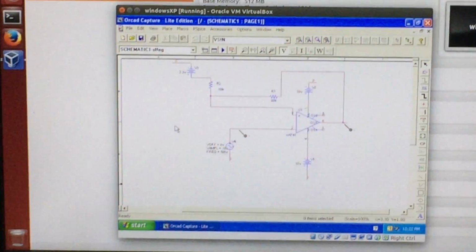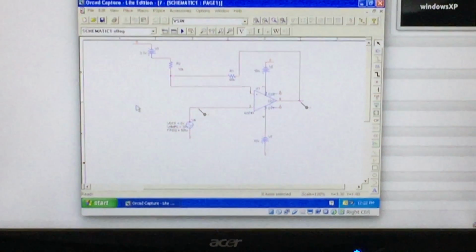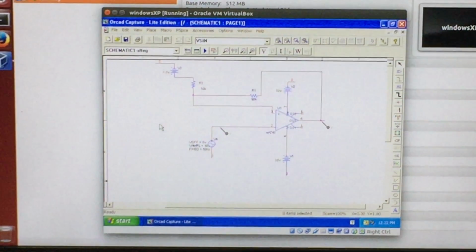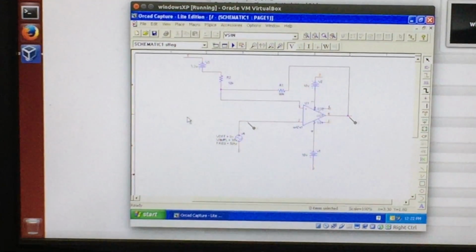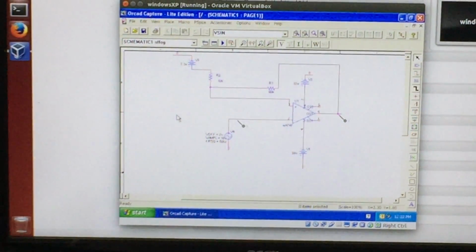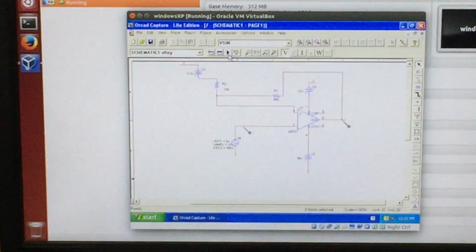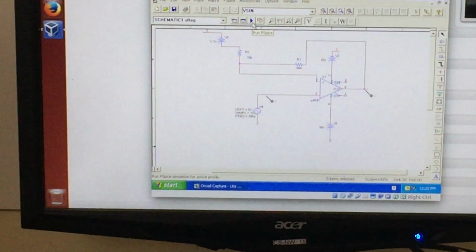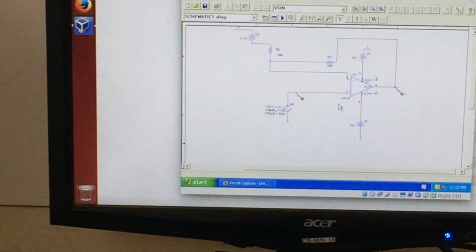Go to the simulation profile, you get a dialog box and you give a dummy value, and then you go to one more window. In that you have to enter 40 milliseconds and 0.1 millisecond as runtime and step size respectively, and then apply and then okay. Come back, cross check everything is okay, then save it one more time, and then you have a triangular symbol there. So you run the PSpice, click on OK.